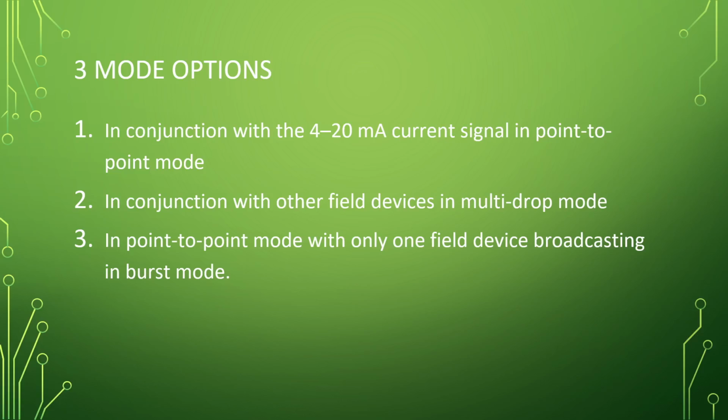It's going, yep, here you go. So you still have that 4-20 milliamp for its main signal, like the really, truly, as far as I'm concerned, super important aspect. But you still have that HART for the rest of the stuff, maybe battery level, or what mode it's in, or whatever other information is going on. Maybe a diagnostic mode to make sure it's actually working correctly. So that'd be mode 1.